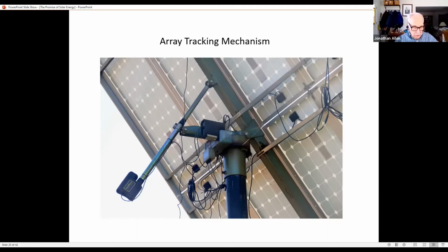Now, there's a whole bunch of alternative photovoltaic cells. Unless the area of the cell is severely limited, for example, aboard a spacecraft, efficiency is not the sole consideration. Would you want to install modules that are just a few percent more efficient but cost 10 times as much? Of course, there are limits. At the other end, just as price can kill economy at the high end, balance of system costs can kill you at the lower end. After all, there's a cost to the extra real estate, supporting structures, wiring, and maintenance.